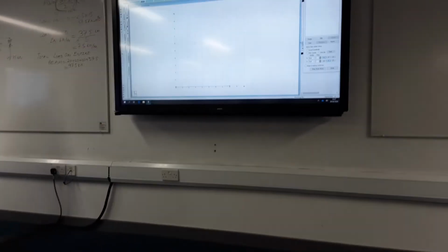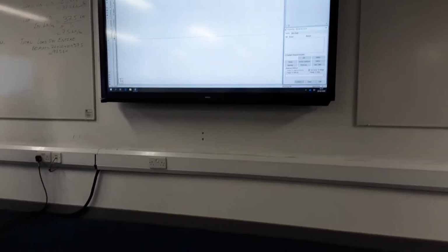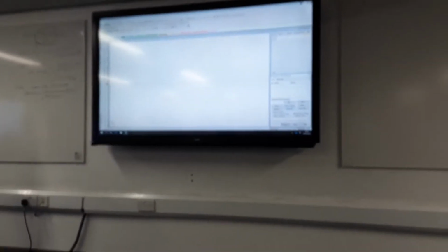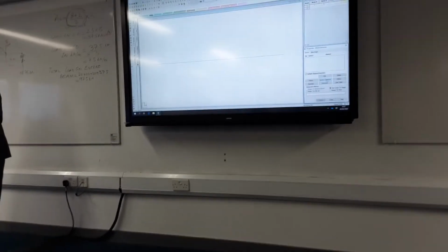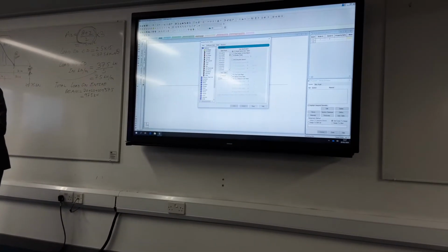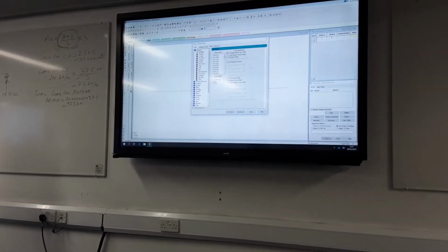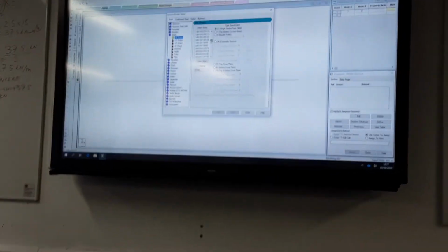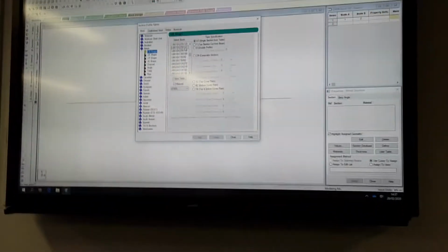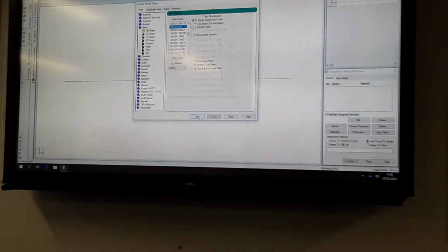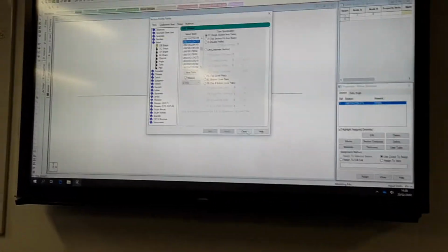So simply go to General and then Property, and then Steel Database. Click on Steel Database, and then some sections will appear. I will go to British sections, and then I can define any section. So let me define UKB 610, 229 and 113. Alright, so simply add this beam and close.